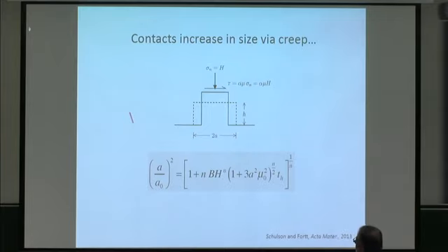And so the model here that I come up with, and I'm not giving you the details, although the reference is here if you so wish, we've envisaged the simplest possible creep law, power law creep, where the creep rate simply scales through the material's constant of stress to some power n. A better description might be a hyperbolic sine function, as Barnes, Tabor, and Walker taught us, or some other function, as others have shown. But it doesn't matter, I wanted the simplest. And there's the simplest relationship one can get. I'll describe it for you in terms of the hardness that the material exhibits. B is a parameter in the power law creep law. I can describe that if you're interested later.